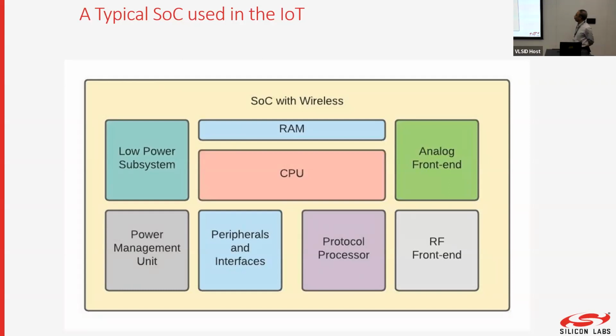A long time back, people used to do IF-based up conversion, converting to intermediate frequency and then doing it. Similarly, the receiver would convert into an intermediate frequency, 50 megahertz, 70 megahertz, 455 kilohertz. These were kind of popular IF frequencies, but today everybody does direct conversion directly from RF to baseband. So this is also important.